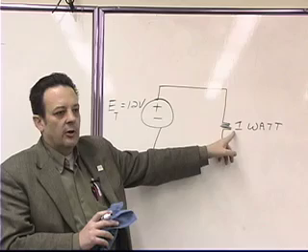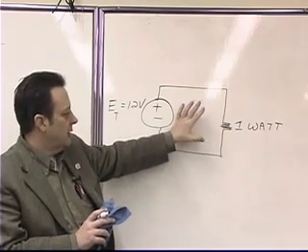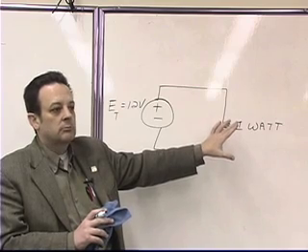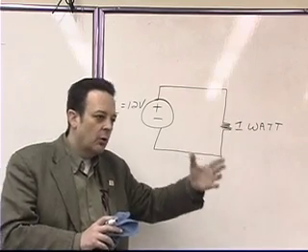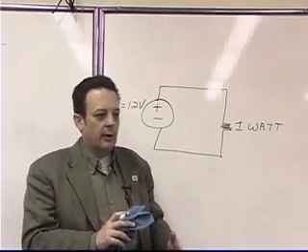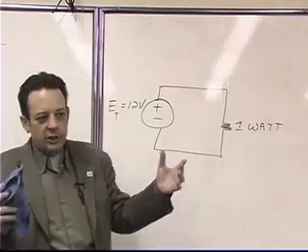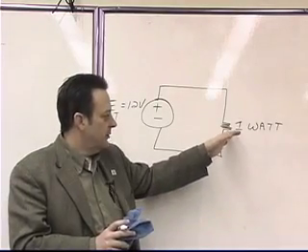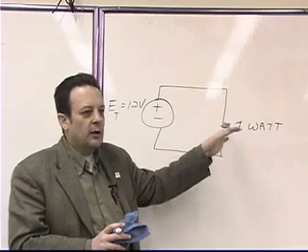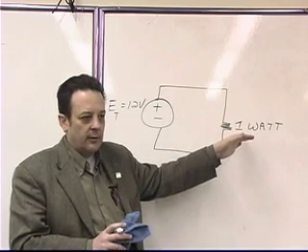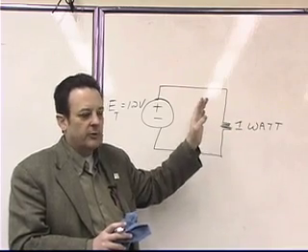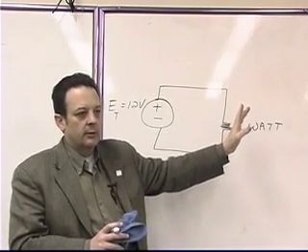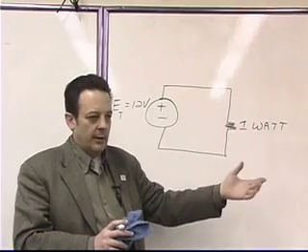Okay? So if this circuit is being used for something that is critical, you know, something involving life support, something involving a heart-lung machine, something like that, right? Then if you know this is going to be dissipating 1 watt, you're not going to put a 1 watt resistor in there. You're going to put a resistor that's rated for significantly more than 1 watt. Okay? You're going to at least double it.